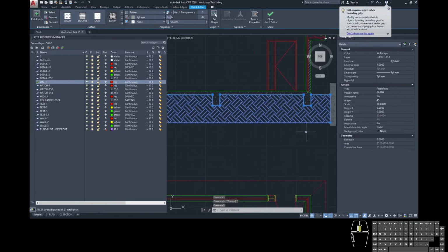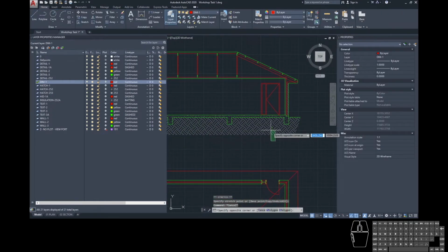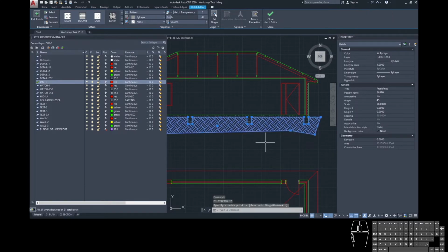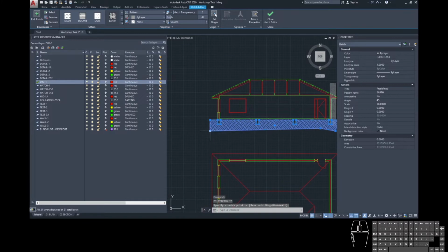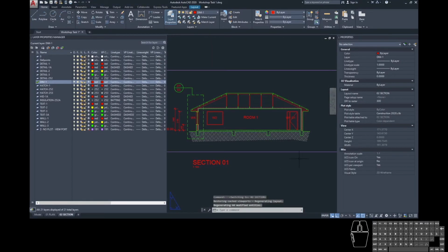The hand-drawn version of this has a bit of a kooky boundary around it. So again, you can remember that you can grab these lines and move them around a bit. You're also able to hover over here and add some extra vertexes. The vertex means the control point, so that you can add in that little bit of flavour here and there if that's what you want to start doing with those hatches. Going to switch back into Paperspace so we can see that we've got our hatches and stuff coming together there.